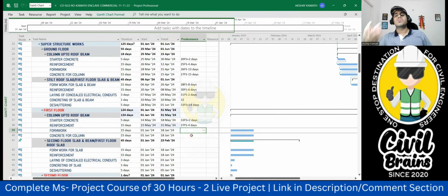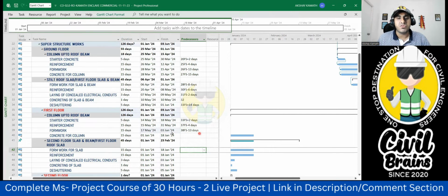If somebody asks you, you have to tell it's a typical quantity. So that is why, floor by floor, we'll take the same duration, same lead, same lag, everything the same. Okay, good. Now come to the form work. So what is the form work? We give minus 13 days. That means 38 FS minus 13 days is a lag. I mean, 13 days is a lead for us.